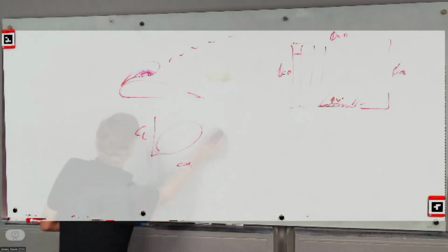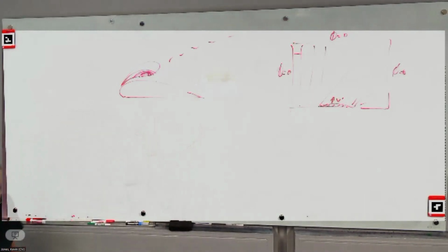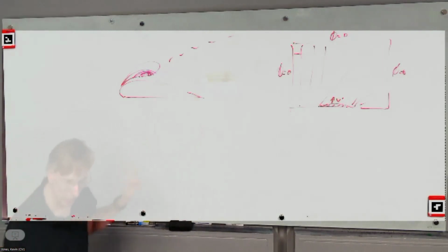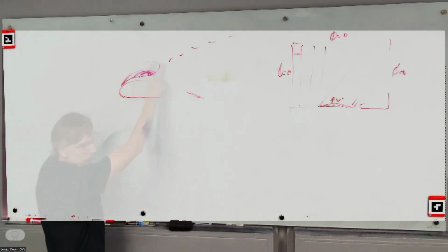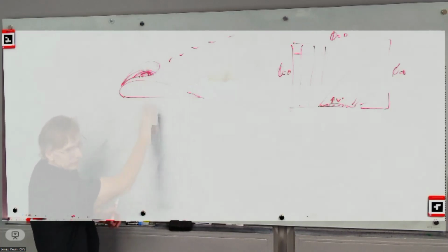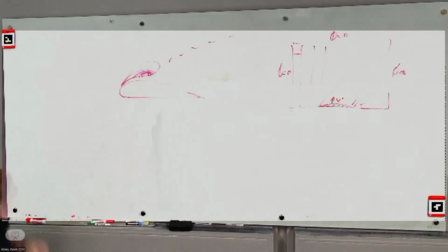In nature, this same thing comes back all the time. You hear all these arguments about how a bumblebee can't fly, right? If you look at little micro wings and try to apply your linear aero knowledge, it's not going to work. So they're surviving on this. The lift can get quite high as long as that vortex is attached. And what they do is they've got the timing down so that by the time it starts to separate, they quit a stroke and reverse and go back. So they're surviving on a vortex attached on this side and attached on this side. The timing becomes a critical thing.